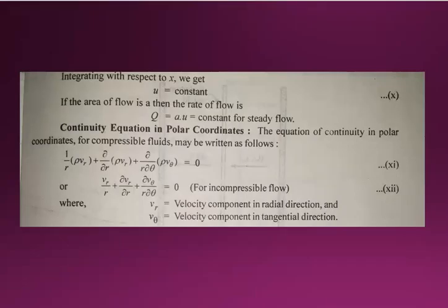When we integrate with respect to x, u is equal to a constant. And if A is the area of flow and Q is the rate of flow, then Q is equal to A u, and is equal to a constant for steady flow.